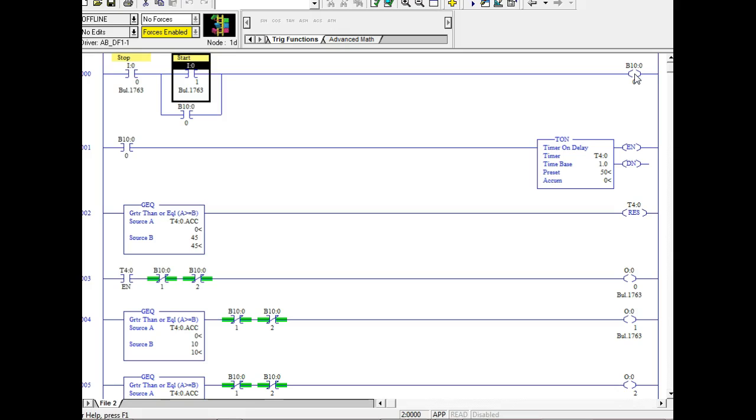So that's what happened to this. I don't know where it's at. But I knew it was in the PLC. But when I did the original drawing, I had all these labels and everything on there, all the symbols labeled, all the comments and stuff like that. Well, since I couldn't find it, what did I do? I uploaded it from the PLC. The PLC itself does not care about symbols. It does not care about comments. All it cares about is addresses, right? Addresses, that's all it cares about.